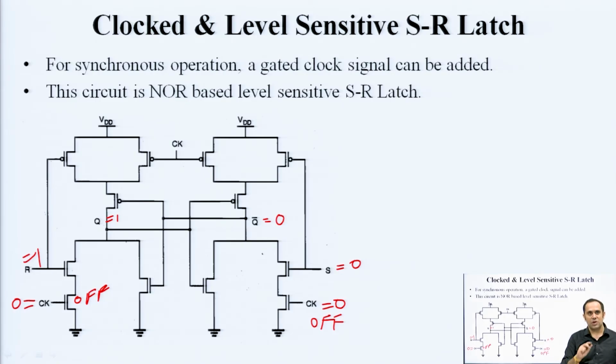but because you are giving a level triggering via the clock, and that clock is off. So, this is positive level triggering. Okay. So, in this case the clock actually avoids the data to be updated. Until the clock triggers, output will not be updated. So, this is how level sensitive latching operation is taking place.